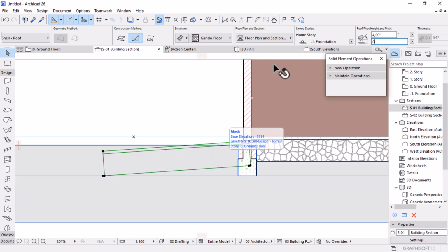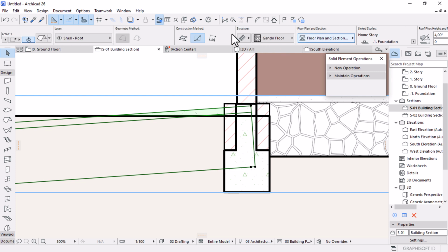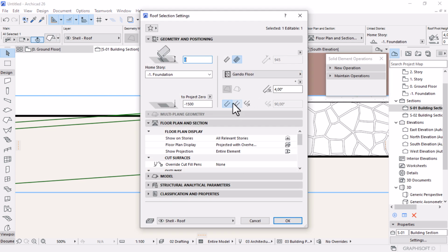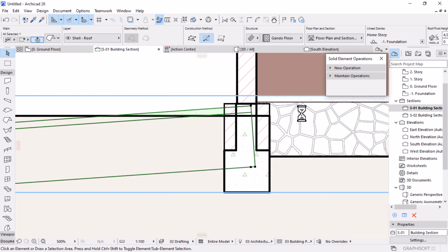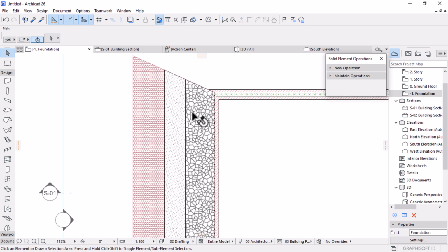And then to correct this mistake or this situation here, we could open the settings and have it plumb. Instead of this set perpendicular, let's make it plumb like that. I hope it works perfectly. And then we can go to the footing and make sure it sits right where we want.